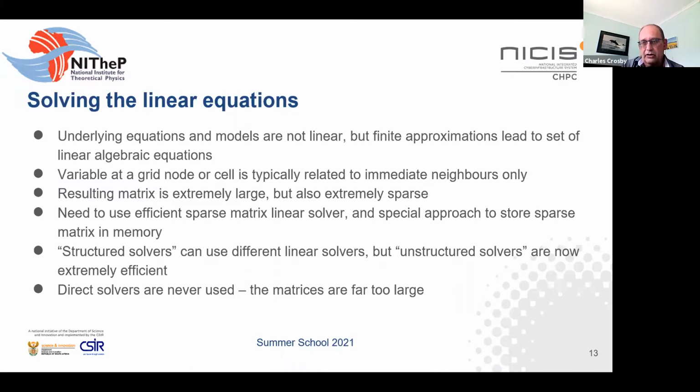So it illustrates the point of sparse matrices. CFD matrices are inherently sparse. If you're dealing with a single dimension, you've only got 3 elements on the diagonal of the matrix. If you're dealing with unstructured methods and more dimensions, you start adding more elements and they're not necessarily on the diagonal. So one of the key elements of solving these equations is to restructure that matrix to get the elements closer to the diagonal, because you don't want them scattered all over the matrix, because that's quite bad from a numerical point of view. Also, from a memory point of view, you never store the entire matrix, you only store the non-zero elements.